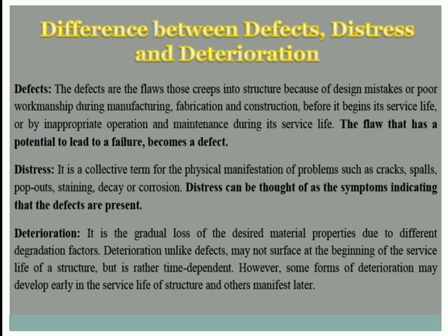Then let us discuss some differences between defects, distress and deterioration. So defects are the flaws, as we discussed. Flaws that creep into the structure because of design mistakes or poor workmanship, fabrication, construction. So the flaw that has a potential to lead to failure becomes a defect.